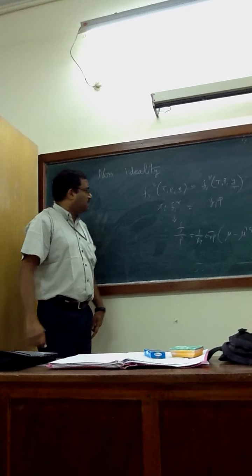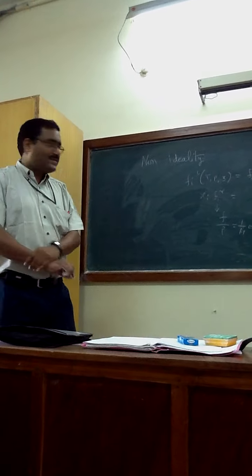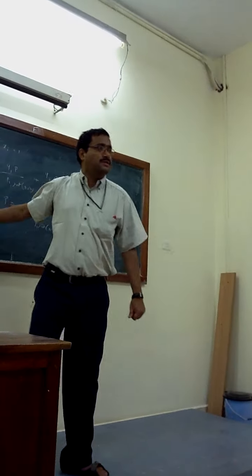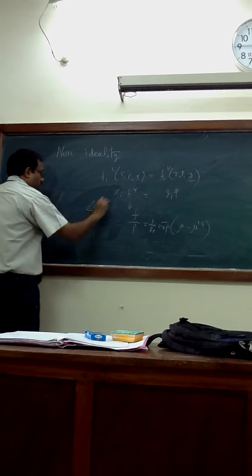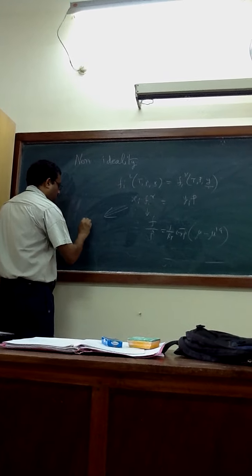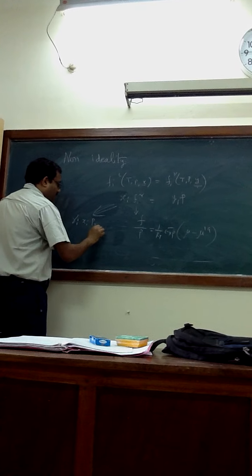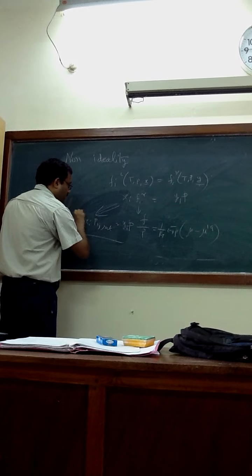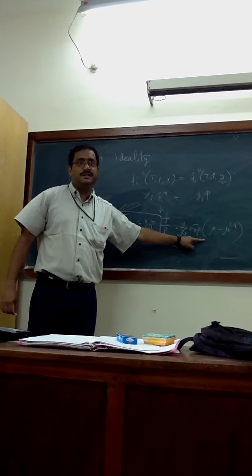What I am saying is that if the liquid phase pressure is not low, then some accountability will be there for this term. So this entire thing can be written with some multiplication factor: xi pi sat equals yi P. Some multiplication factor will be there because of this.